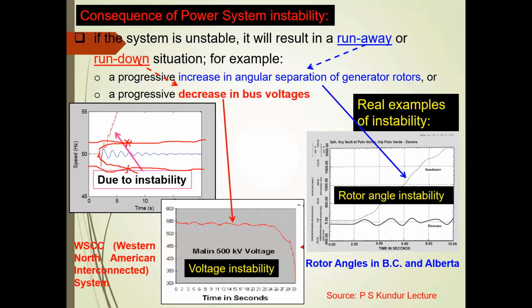Normally, we don't have any delay, because the relays operate in milliseconds. But the deviation in the frequency, the profile of frequency change, all depends upon how the governor responds and what is the amount of load disturbance.